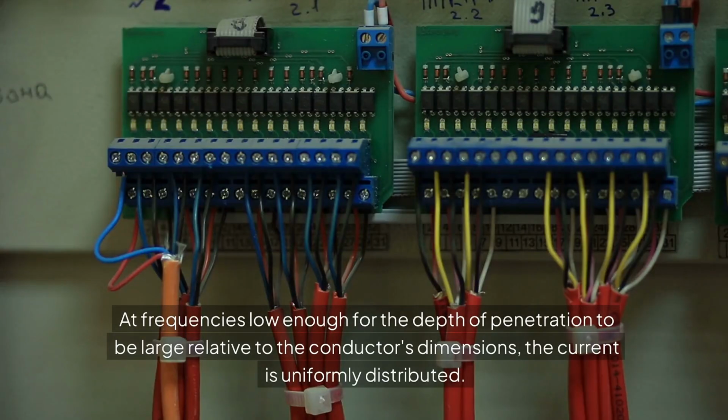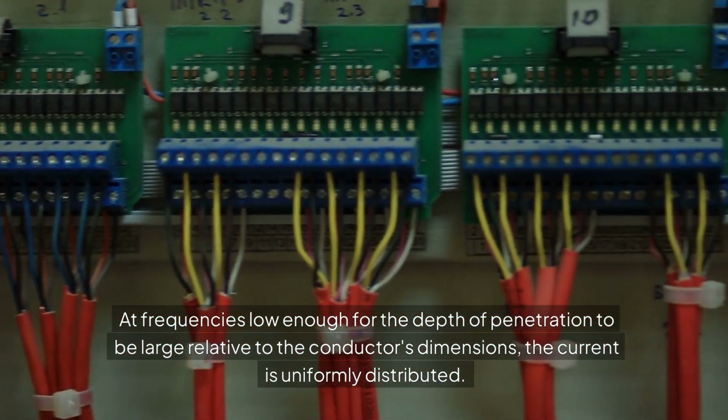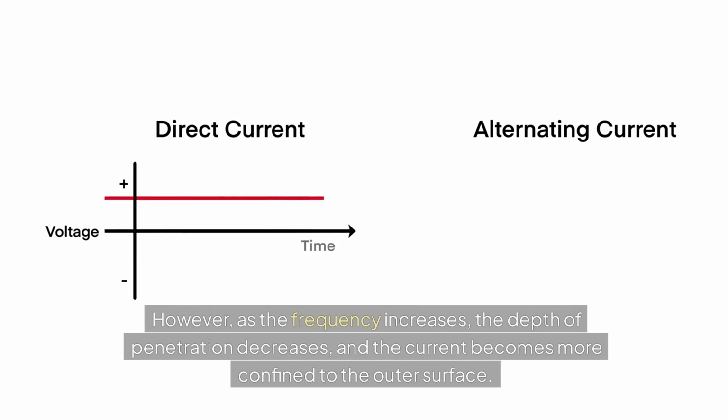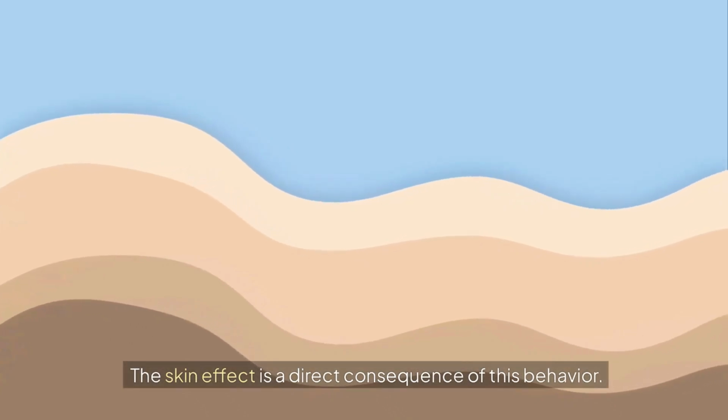At frequencies low enough for the depth of penetration to be large relative to the conductor's dimensions, the current is uniformly distributed. However, as the frequency increases, the depth of penetration decreases, and the current becomes more confined to the outer surface. The skin effect is a direct consequence of this behavior.